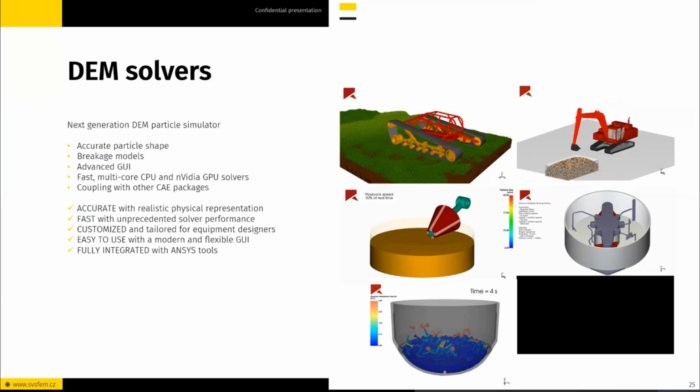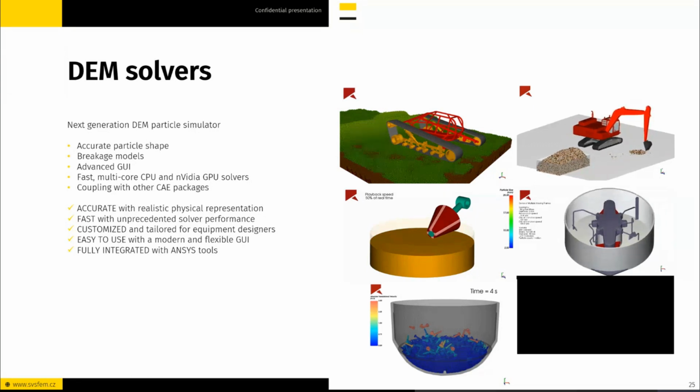If you have a precise, systematic simulation, then it is up to your choice how detailed the physical description of the component will be. You can choose the approximation method, or you can combine several methods into some holistic and hybrid solution, where the optimal methods are used for specific subdomains, boundaries, or conditions. One such robust method is the discrete element method, where the domain can be solved on a Lagrange or Euler domain with simplification to individual particles and their response. This approach is very useful when you need to simulate thousands or billions of particles which interact and can break or interconnect. Then you can ask what the wearing of the tools is, what the reaction forces are, or what the stable pile angle is, for example.